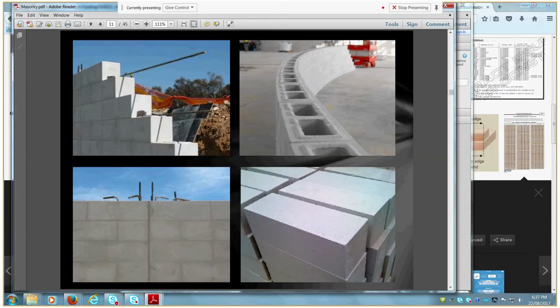Typically, with your concrete blocks, one possibility is to core fill the blocks. So they're used essentially as a concrete formwork for the core filling. In that situation, we have vertical reinforcing with a cog, or in this situation they've got a vertical reinforcement with a cog on the end, I assume to bond into a concrete slab to be cast on the top.